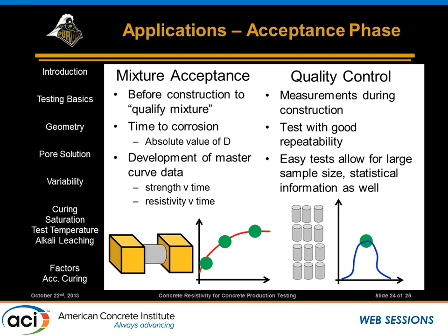It's easy to test this and it's easy to know, have you lost moisture from the time that the sample's been prepared, because you can simply weigh the sample at the beginning and the end, and it can give you indications on what variations have taken place during the construction process to try to bring that back to how those changes may affect the service life of the particular element you're looking at.